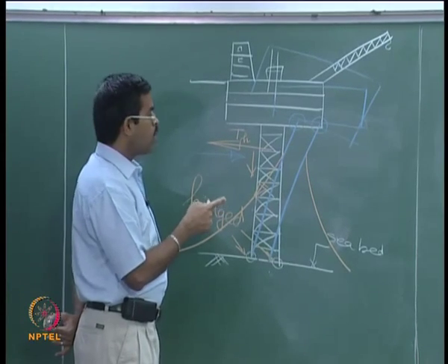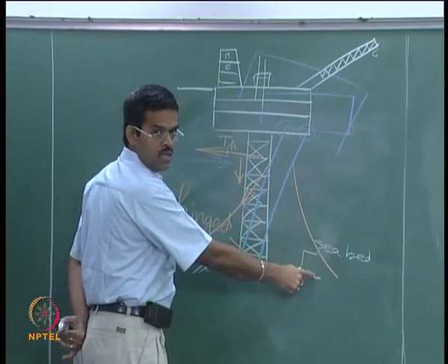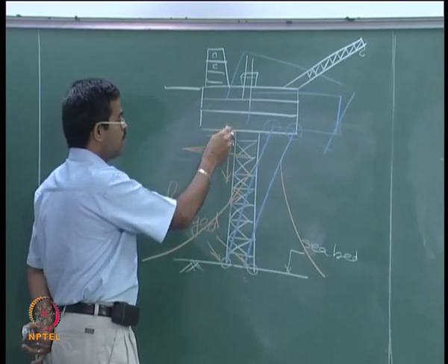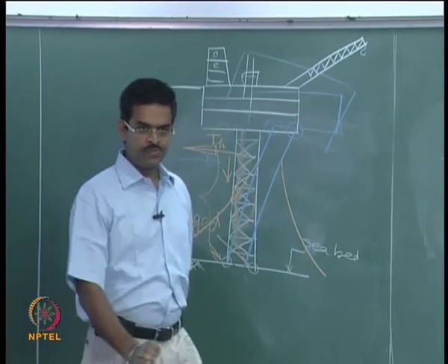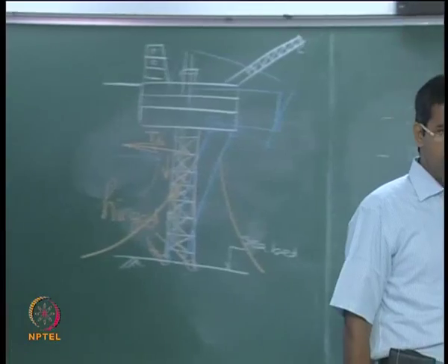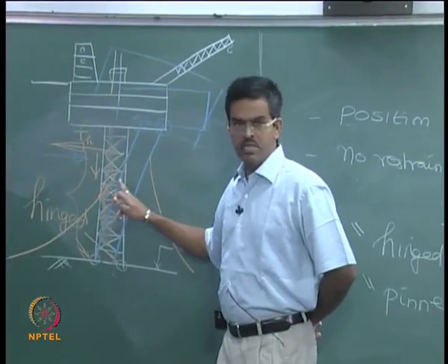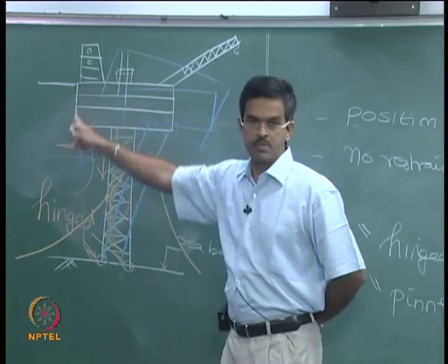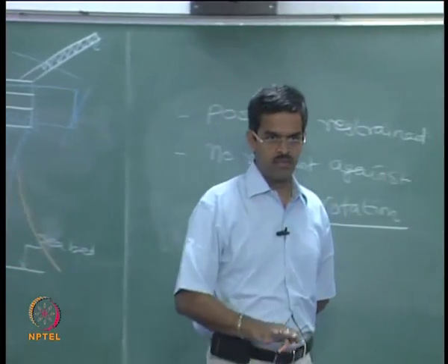Okay. Now, what is the advantage of introducing a new member which will take care of the lateral force? Greatest advantage is my lateral forces do not come on this member, is it not? If it does not come on the member, it has to be designed only for the forces generated by its own weight or by the top side. It means the member design becomes less complex.